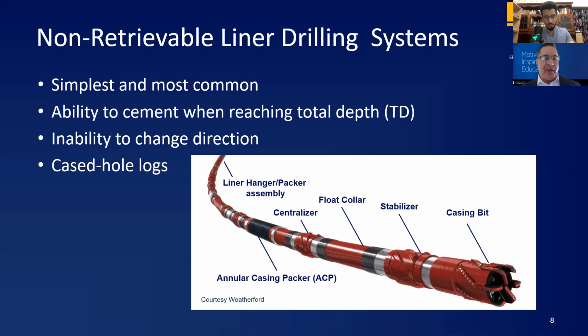Reason being, it's a lot stiffer. The liner BHA, the liner itself, is a lot stiffer than conventional BHAs. So it's going to be less predisposed to turn in a certain way or build in a certain way. However, there is BHA modeling software that you can design these liner drilling systems to have a build, a drop, or maintain neutrality while drilling. So there is software for that.